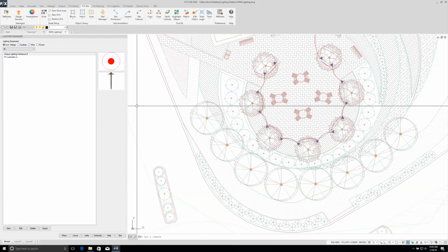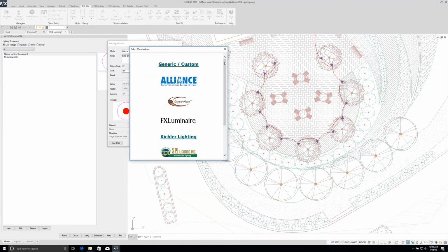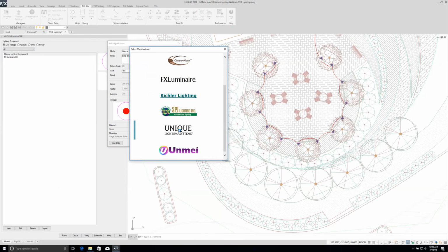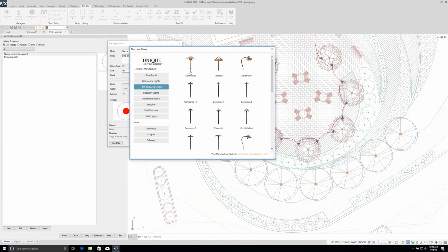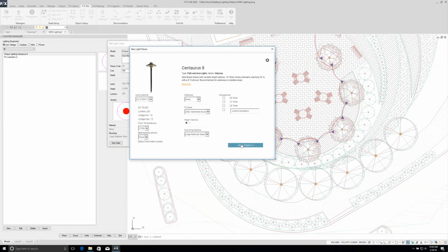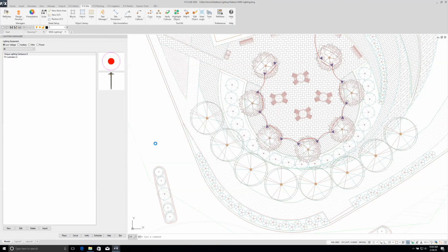Maybe I need to re-add the fixture in. So that brings me to a good point here. If you ever need to replace the fixture, you can edit it and click on the replace fixture, and then go to, you're probably doing it with a different fixture, but you can also, if you're just updating like I'm doing, go to that fixture, click on it, add it to the project, and it's going to update that piece of equipment.